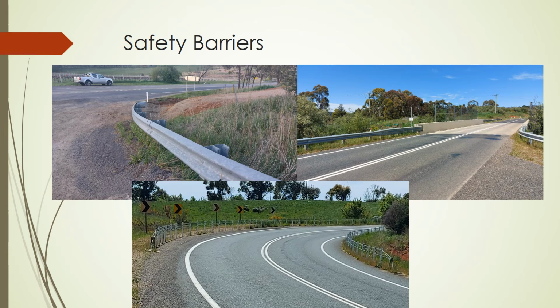Now, the embankment construction does require safety barriers to ensure the safe transit of vehicles so they don't run off into quite a significant fall. We've got a few options, and concrete barriers are protecting, you can see here, the bridge. They're very strong and very durable with little ongoing maintenance, but they're a higher expense, and when they are damaged, they're a massive headache to repair.